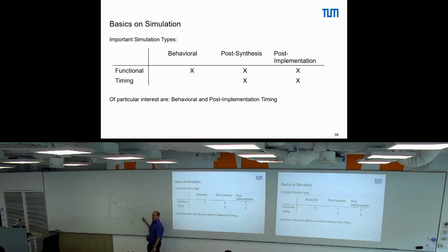Something unclear? Just interrupt me, so that I don't make a mistake somewhere. Seems okay? Okay, good. Sometimes there is just some mistake, some typo that I overlooked there. So this is the maximum delay we have. Following the same logic, the AND is most likely faster than the OR, so there is a path, probably assuming this delay is equal for all, which is somewhere here, which we call TD minimum.